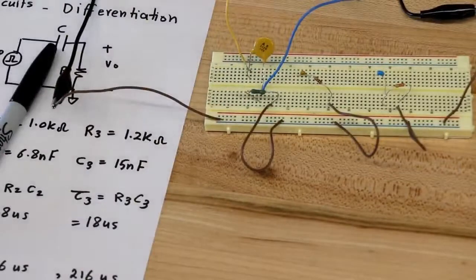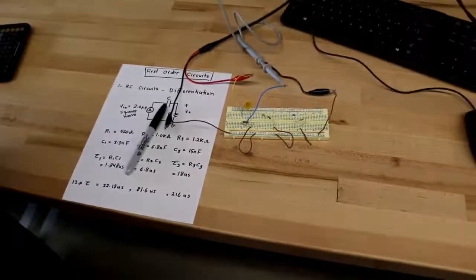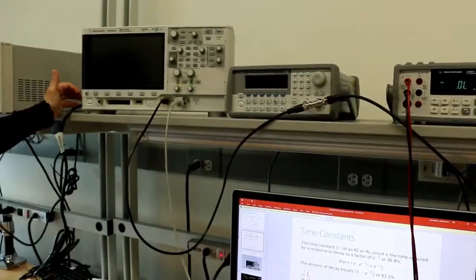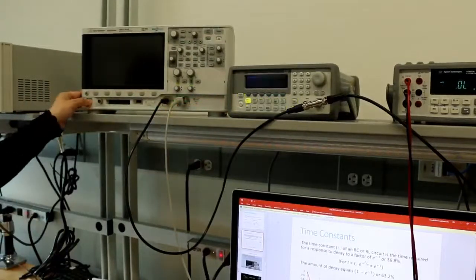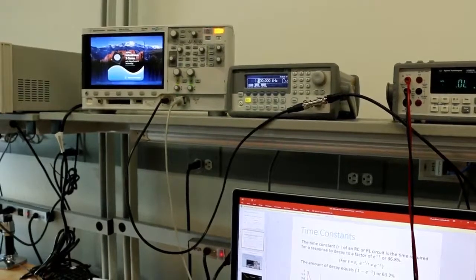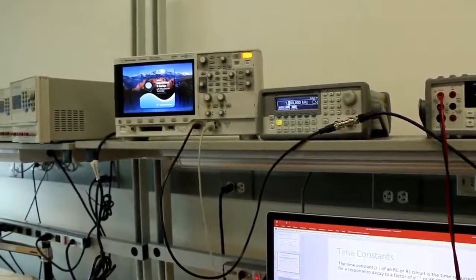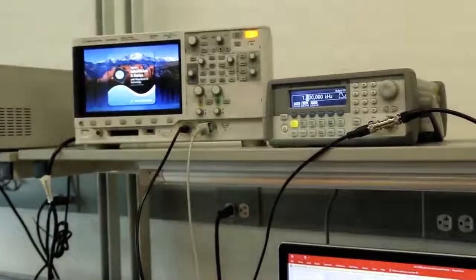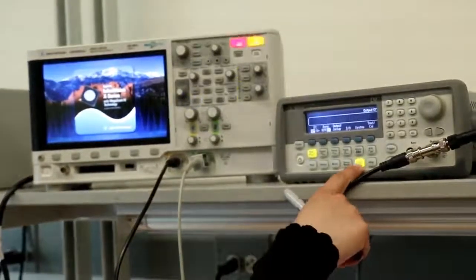So for this circuit, we'll need the function generator, and we need the oscilloscope. For the function generator, we need to set the voltage to a square wave, 2 peak to peak, and instead of setting up the frequency, we'll set up the period, and the period should be 12 times the expected tau for the circuit. So first